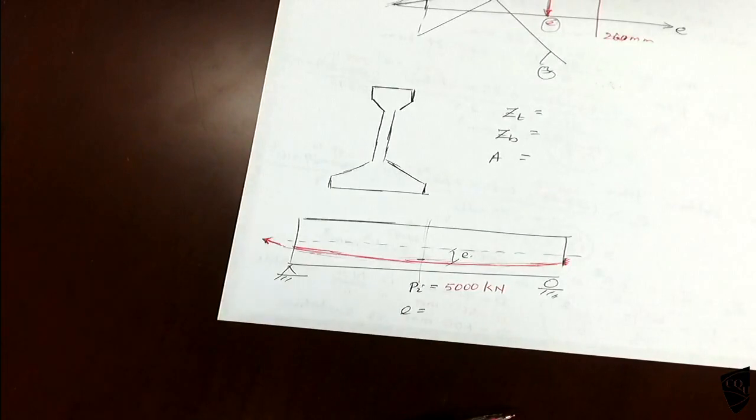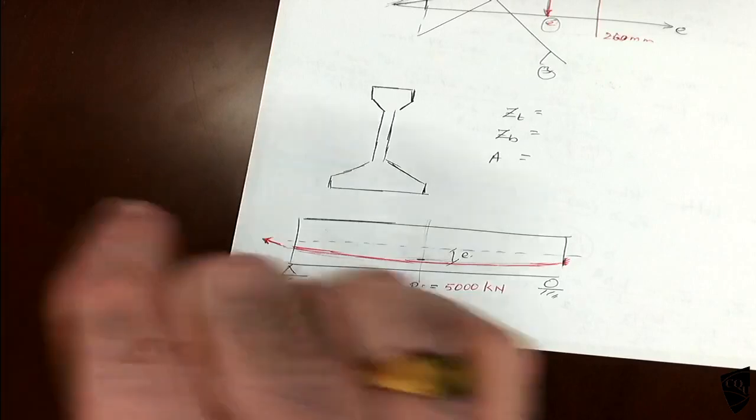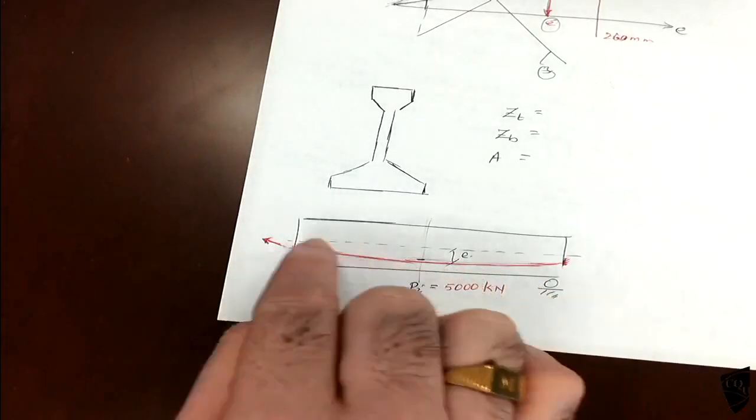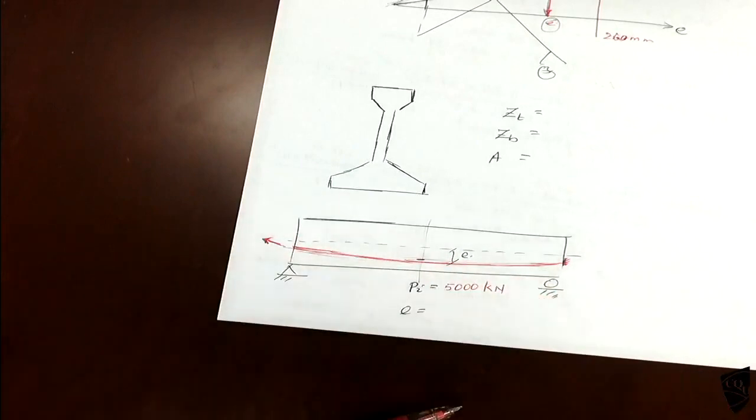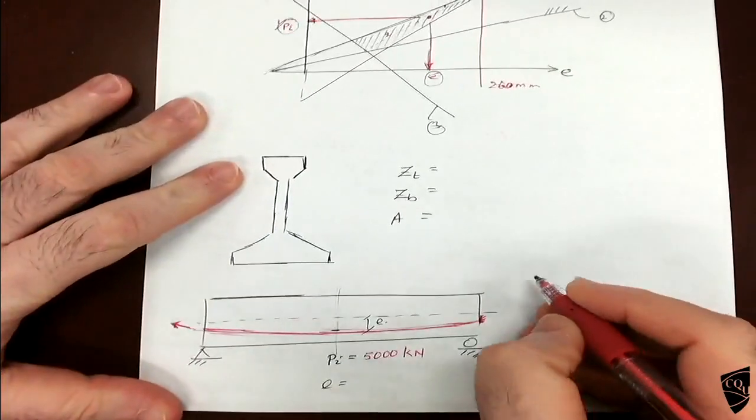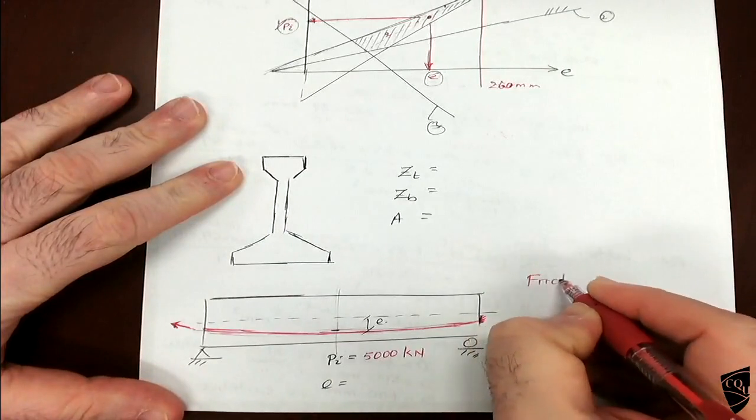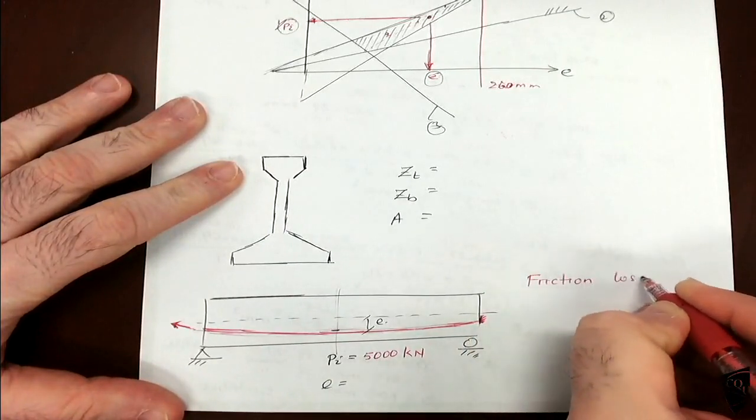But when you work out the post-tension case, you will put a duct, like a pipe, and put the steel through that. So when you have a pipe and you insert the steel through it, and you pull that one, what will happen? There will be some friction, some friction loss.